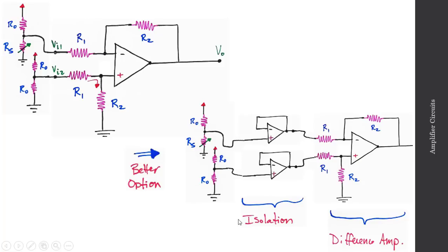This entire circuit is what's known as an instrumentation amplifier. Now we have the ability to do our difference amplification, but we also have these high impedance op-amp circuits, two of them in fact, with these unity gain buffers, such that now we're properly connected. The sensor is seeing an input of a very high impedance, and the output to my difference amplifier is a low impedance.